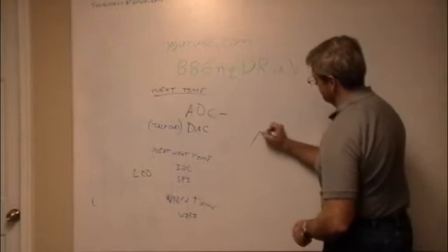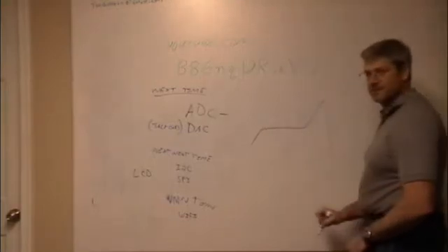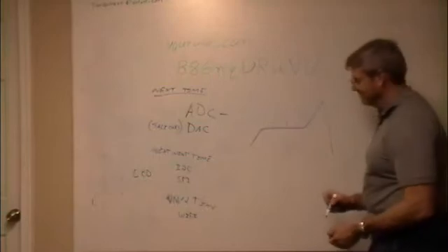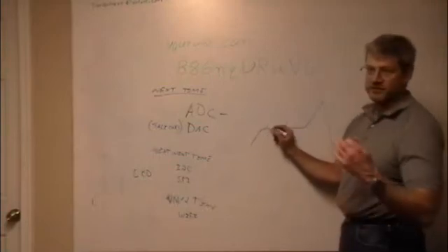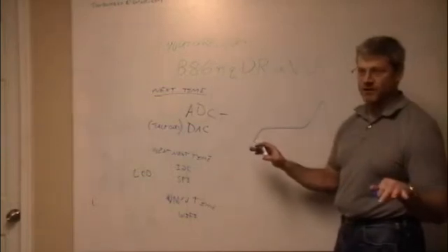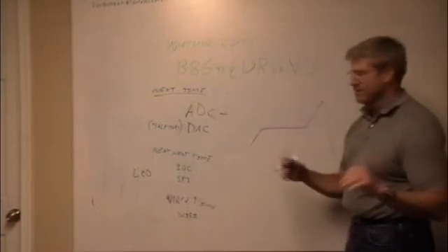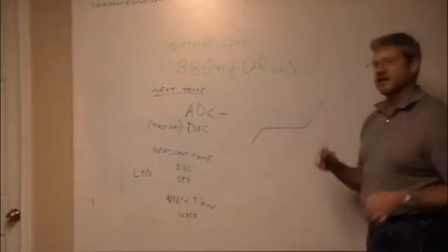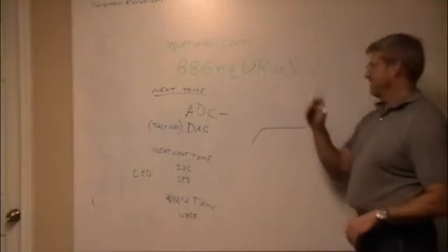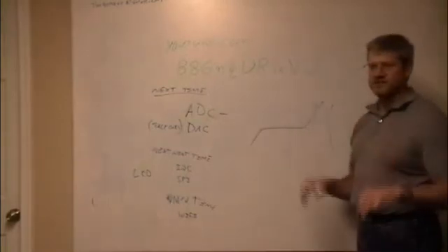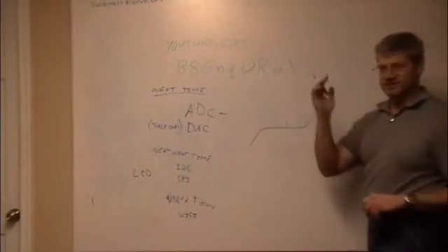It's always linear. So the very first thing I'm going to tell you, I have a homemade solder oven at home. And it has a process time that does something like this. So you could call that a composite cure cycle. You heat up, get everything to a steady state temperature. You bake it for a while. This is called the ramp up. This is called the soak cycle. You soak it because when you go here, you're getting really hot. And you don't want to thermal shock everything going from here to here. So then you bring it up, and then this is a really short time, like maybe 25 seconds, and then it just turns it all off and lets the heat out.